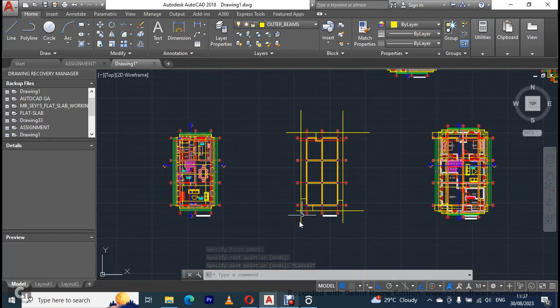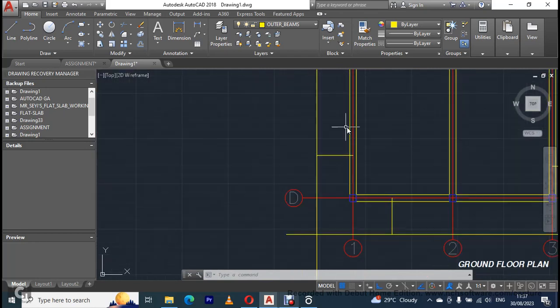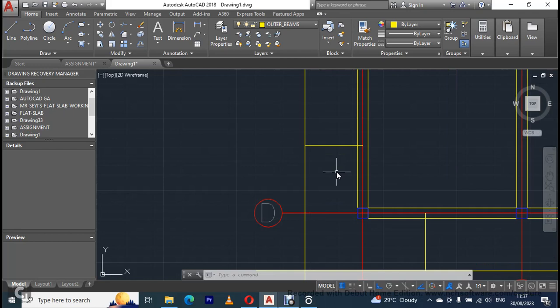So we also have to do some alterations on our beams. Since our beams are connected to slabs, I don't know if you guys have worked with design of slab structures using BS code, whereby there's a particular portion where it says one edge continuous and the other edge discontinuous, things like that, and then there's a particular coefficient that you're supposed to work with. So that's what we're working with here.